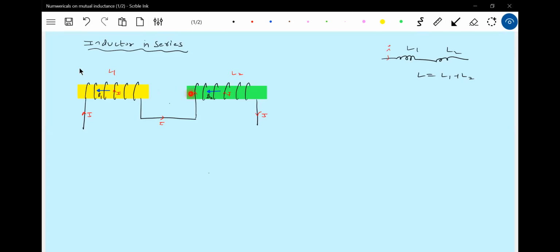Can you remember? And if they are very close, definitely, if there's a varying current, the magnetic field will be variable. A varying magnetic field will link this solenoid 1. The field produced by solenoid 2 will link solenoid 1, and the flux linking solenoid 1 will change. So there'll be an EMF induced. Yes, we should also consider now the mutual inductance effect here. So let the EMF induced in this solenoid be E1, and the EMF induced in this solenoid be E2. What is E1? We'll write the equation.